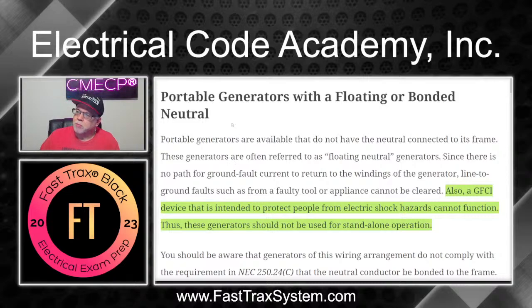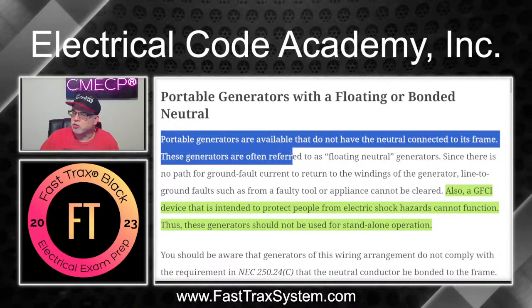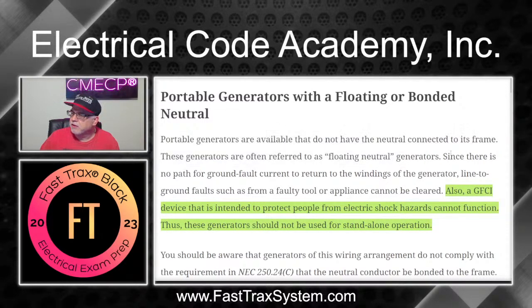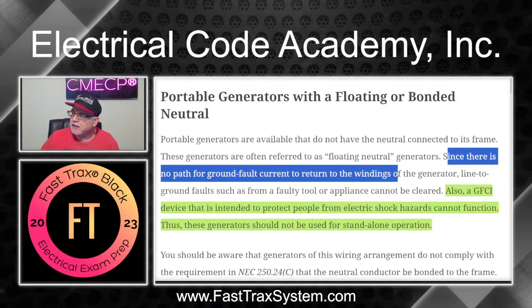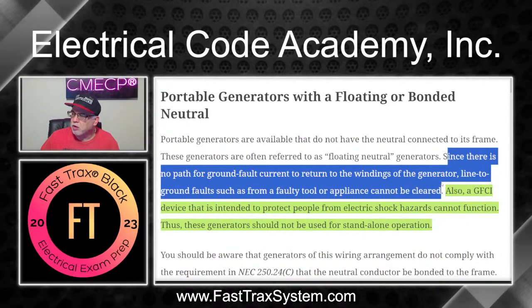Now, portable generators with a floating or bonded neutral. Portable generators are available that do not have the neutral connected to the frame. They're available out there. These generators are often referred to as a floating neutral generator. Since there is no path for ground fault current to return to the windings, to get back to the source, because it doesn't have that jumper, okay? Then line to ground faults, such as from a faulty tool or appliance, will not be cleared.